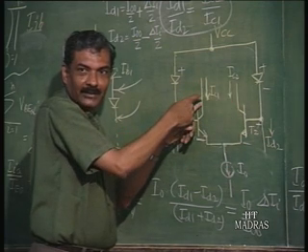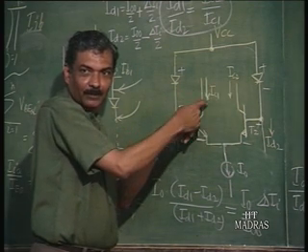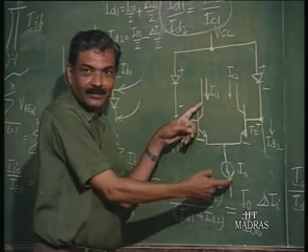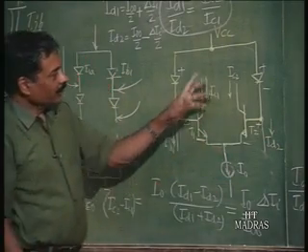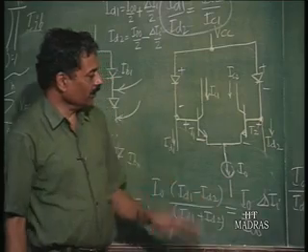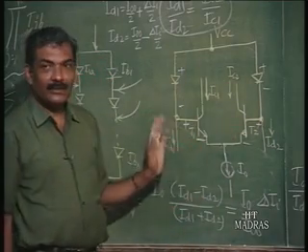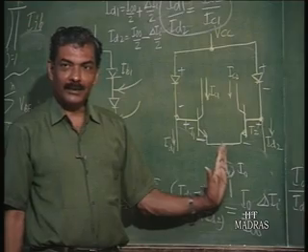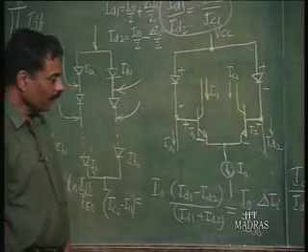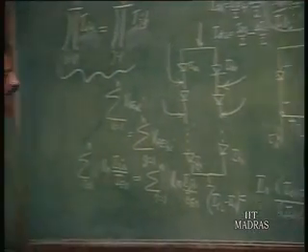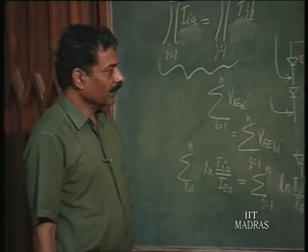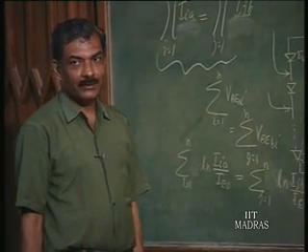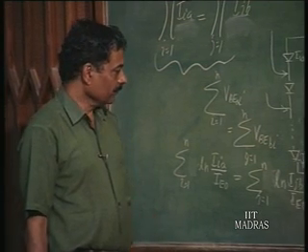This has now, as you see, a differential input and a common mode input. Common mode input is nothing but I naught. So, this can become the input to the next stage, and that will look exactly like this, with this current operating at a higher value. That much should be sufficient for Gilbert's gain cell. Now, how to use this for a multiplier is something that we have to discuss.